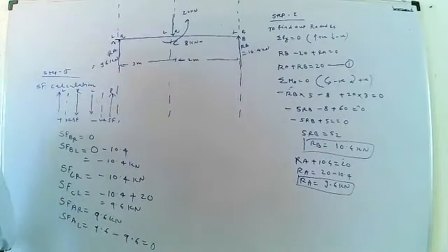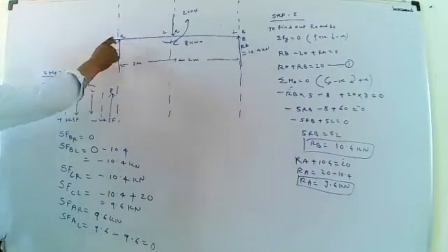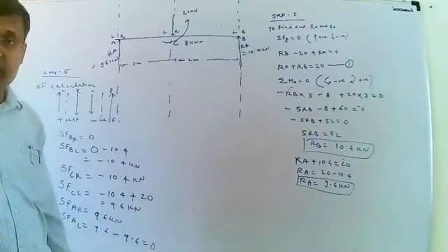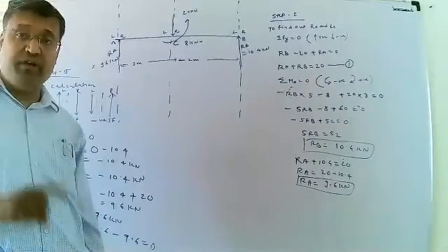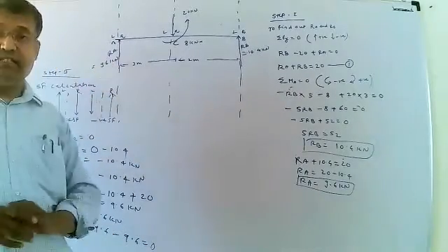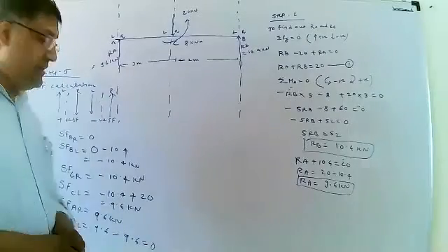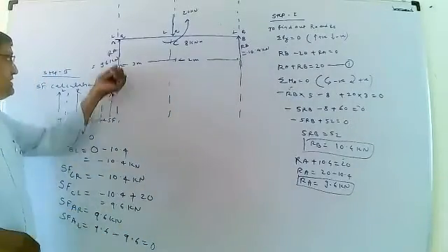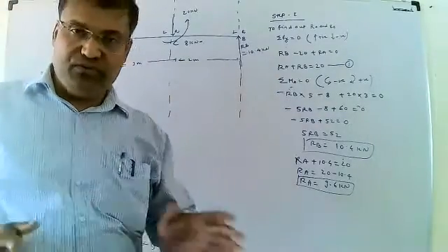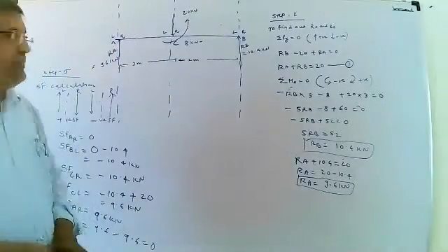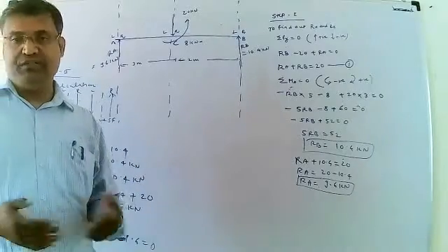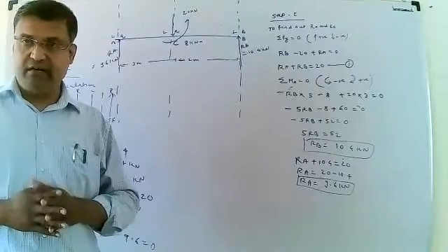9.6 kilonewton. Then here at the point A, upward force is given. The value already calculated in the first step according to equilibrium condition, RA, that is equal to 9.6 kilonewton. Then 9.6, that is upward force. 9.6 minus 9.6, that will be equal to 0. Then shear force at the end point will be equal to 0. Your calculation regarding shear force will be correct.